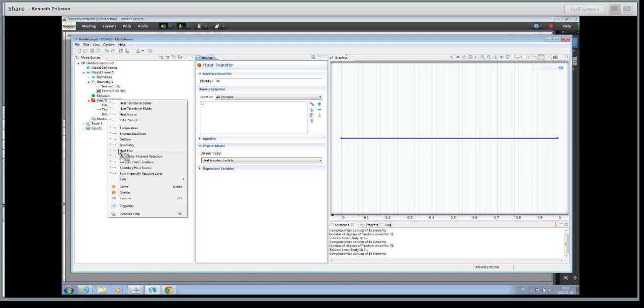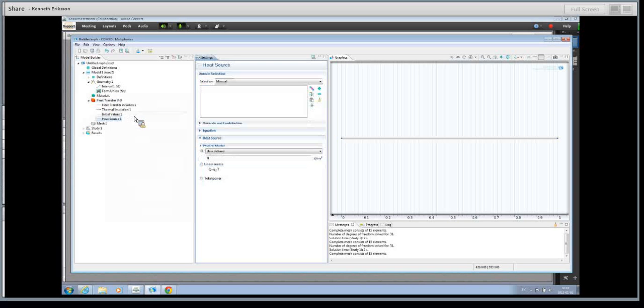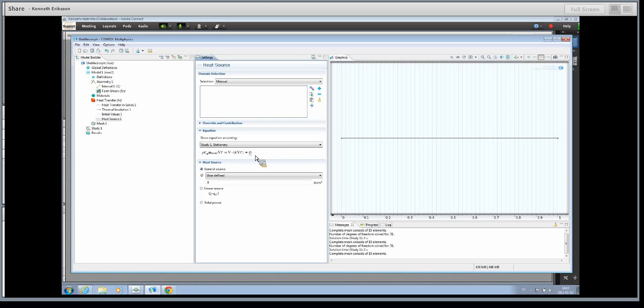So I left click this one, and there is an equation here for the heat production that we see here. First of all, I mark this domain here, and I add this to my selection. It's here. And I now specify a user-defined heat production intensity, which is constant 2.